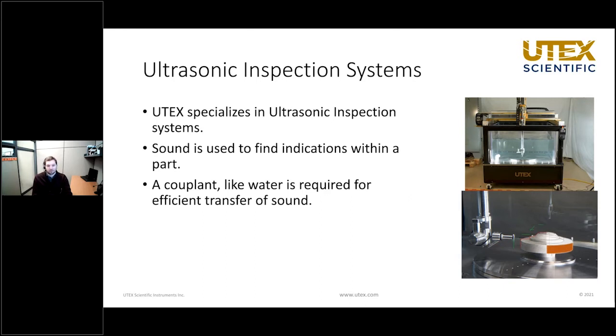When inspecting a part, you get a baseline signal based off of a standard. When the sound meets an indication in the part, the ultrasonic waves are no longer going to return to the probe, but scatter, reducing the signal we see on screen. Depending on the size of the indication, the part will either be accepted or rejected.